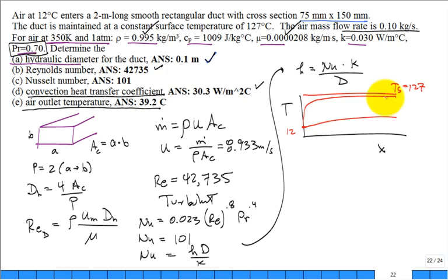But we already worked the math, didn't we? Didn't we already get an equation for this? Let me get rid of this one. Let me draw it like this. Isn't that theta? Didn't we come in with an equation that theta at any location X, we're going to be interested in evaluating at L, so you might as well say theta at the exit is equal to theta at the inlet times e to the what? Minus h, P, L, using L instead of X there, divided by m dot c, and I forgot the minus sign. Does that equation look familiar? Yeah, that equation looks familiar, doesn't it?